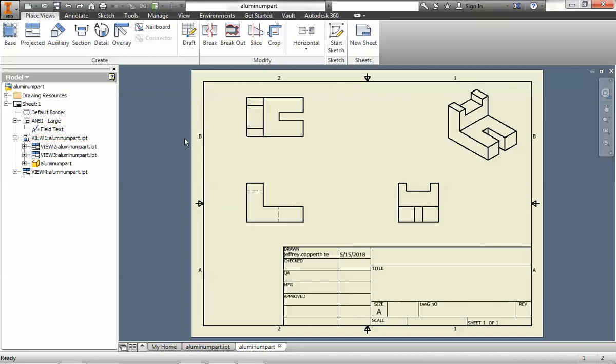All right, so that one here, I can do that. I'll show you a couple other things that you're going to want to do in your drawings. This part's pretty easy, but I'll show you a couple of views you may want to use also in your drawings. What you have to do in your drawings is also add dimensions to them, so that the user knows what the dimensions are. Now obviously everybody's got different parts, everybody's doing different projects, so ultimately you have to ask yourself when you're doing the drawings: is there a way for the user to see the dimensions of all the aspects of the part that you're putting on the page? If the answer is no, that means you need to add dimensions to it. So obviously right now you have no idea how big this part is or even what the scale is.